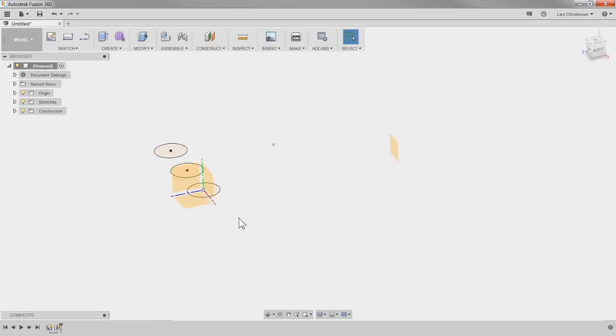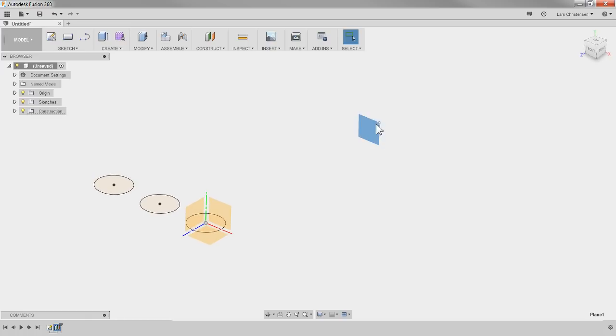So now we have the 3 circles sitting with the origin right there, and then we created that offset plane 300 away. That was that command up there. And somebody pointed out to me in one of my videos that if you select a plane and hit the corner, you can drag the planes bigger, which makes it a little bit easier for you to see. Okay, so one sketch, an offset plane.